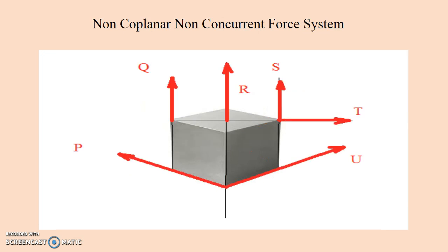This is a very general case, the non-coplanar non-concurrent force system, where the forces acting are not parallel to each other, nor pass through a common point, nor are on the same plane. So the forces in this system act on different planes, pass through different points, and are not parallel to each other. Hence it is a non-coplanar, non-concurrent, non-parallel force system.